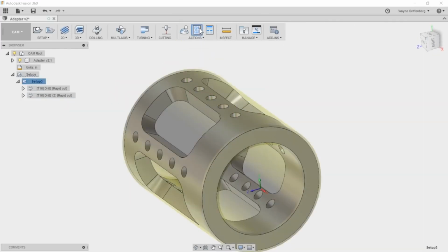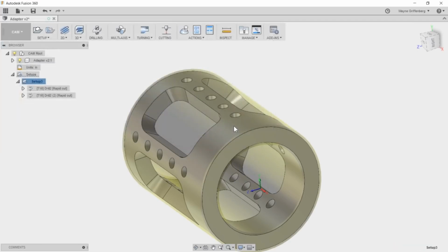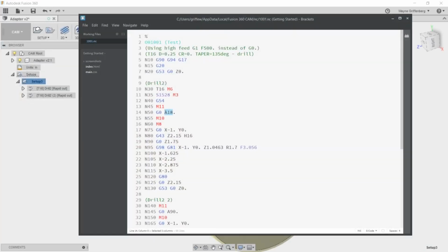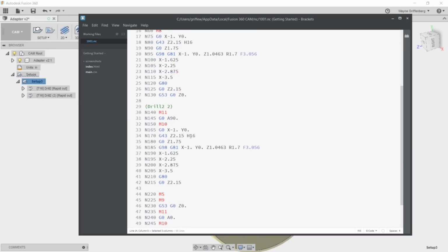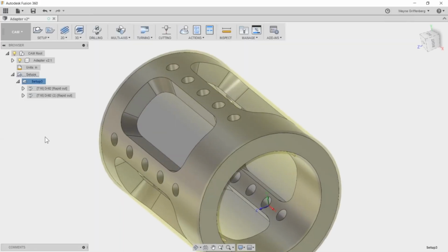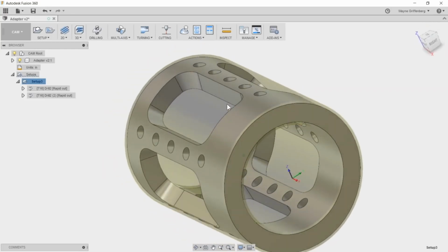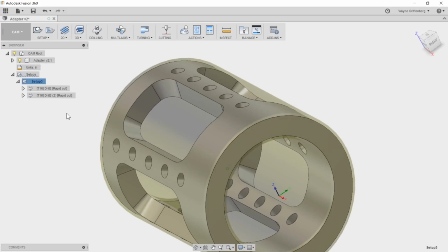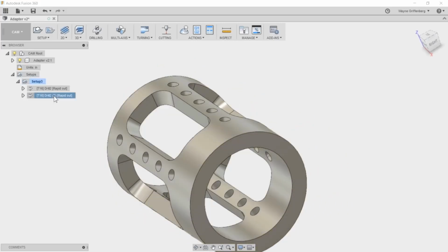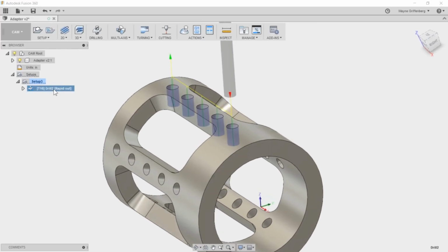And of course, if I post out both of these, now you'll see in the first one, there's the A18. And now in the second one, we're going A90 degrees for drill number 2. And then we're returning back. Now you can think, well, I can do that. Now I'm going to copy 5 of these down, and what if I have different holes and so forth? It could be a pain. Well, here's another way you can do this in a nice way. I'm going to delete out the second holes I did, and now I'm going to make them into a pattern.